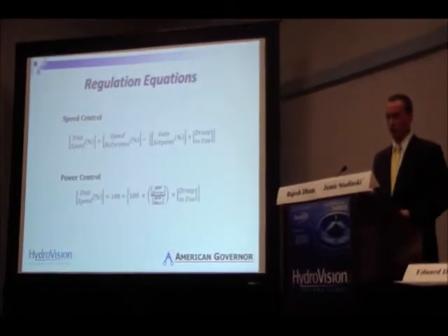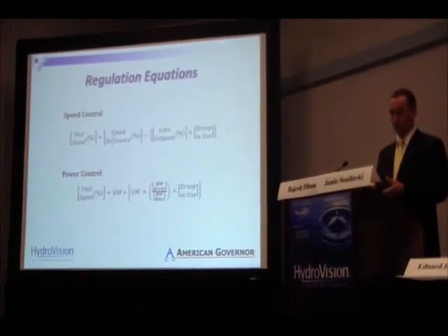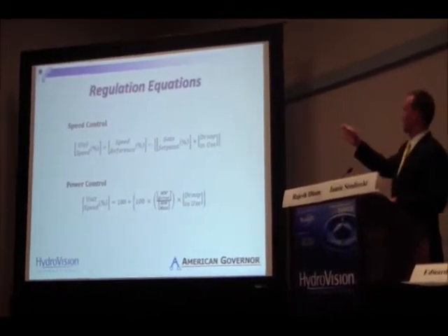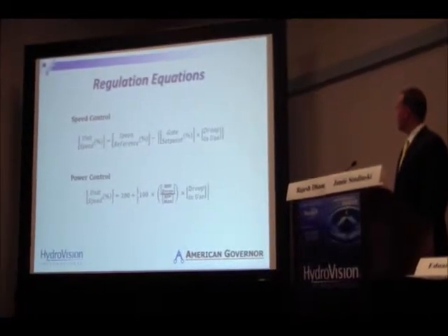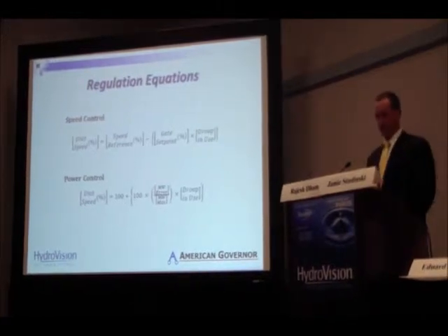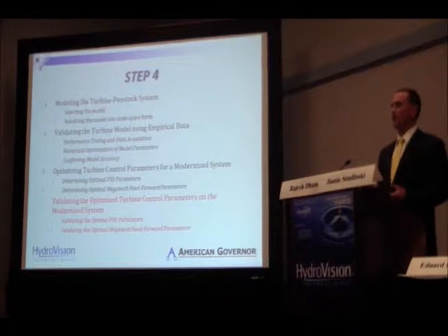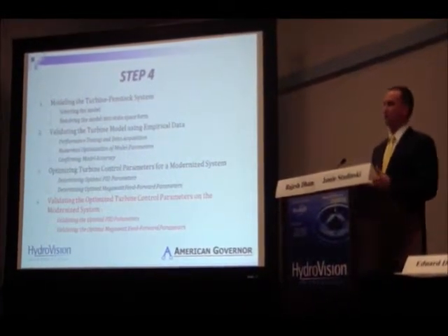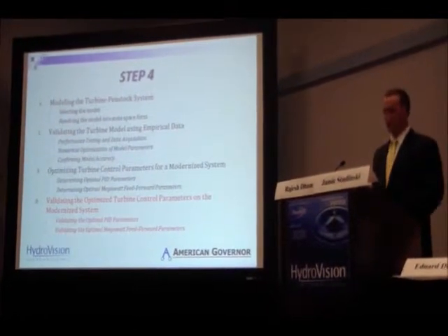And here we're just showing the regulation equations that we use. In order to get into the system and start messing with things, we can see if we're talking about regulating speed, we have a speed reference that we can adjust virtually and see how the system responds. And in power control mode, there's an inherent megawatt set point which we can adjust and play around with. So really, once we were able to develop that model, we could go in there, play around with the gains, with the settings, and tune our system, tune our virtual power plant before we got to site.